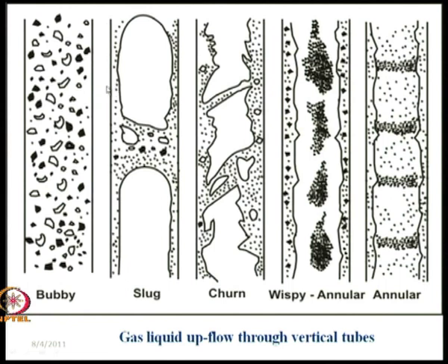In this region the wall shear stress is upward, in this region it is downward, again here upward, again downward. So with position the wall shear stress keeps changing its direction. This is also one particular way of distinguishing or identifying slug flow from the other flow patterns.